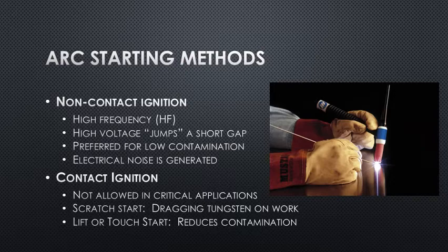This does generate some electrical noise, and high frequency has been known to interfere with computers and nearby electrical equipment. So sometimes special grounding is required, and if that's not possible and you're still noticing some interference, you may want to change to a contact ignition. Contact ignition is not allowed in some critical applications, but for the most part, done properly, it can be done with success without major contamination.